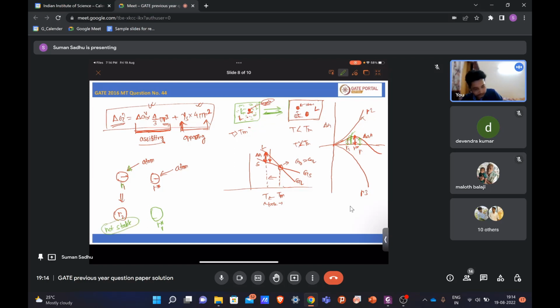But for this R star, now if you add one more atom, its radius increases and it is here. So now what is happening? Here the radius is increasing, but your free energy is also decreasing. It is not increasing. After R star, means after this point, as you increase R, your free energy of nucleation is decreasing, right? So that means it is favorable. So this is stable.